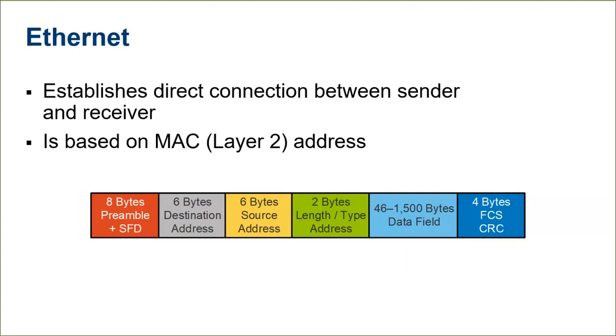A cyclical redundancy check, or CRC, is a unique number generated by applying a polynomial to the pattern of bits that make up the frame. The same polynomial is then used to generate another checksum at the receiving station. So if the two CRCs agree, we know that the data message has been accepted and is valid.